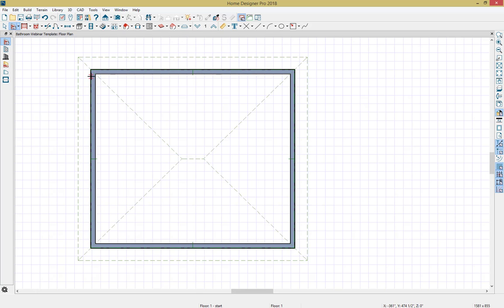You'll see that when you connect the walls, there may be green dashed lines that appear. These show that auto rebuild roofs are on. You can turn them off if you need to through the layer display option. To deselect an object, simply press the spacebar on your keyboard, or you can press the Select Objects mode at the top of your screen.